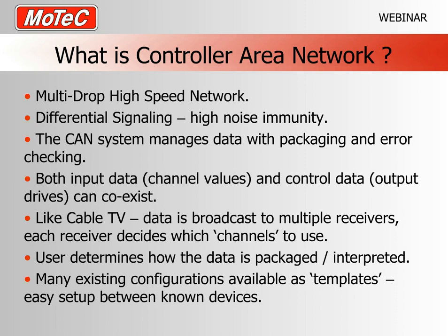Now, CAN systems have a lot of background functions that we as the users aren't aware of, and we don't need to be aware of them. So the CAN system is not only an electrical specification, it also specifies how the subsystem will manage the data. So we as users don't need to manage the data. The CAN subsystem manages the data, and that means it packages the data, it looks after the error checking and error correction, and it looks after making sure the bus population all behave in the correct way and that the bus does not get overloaded.